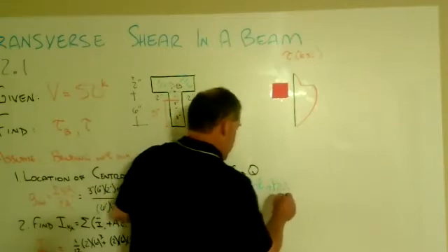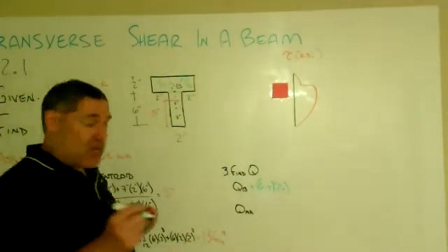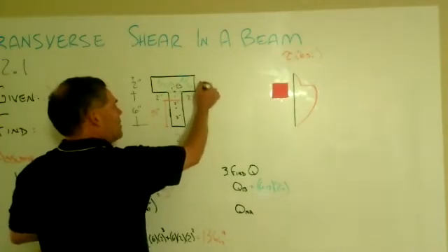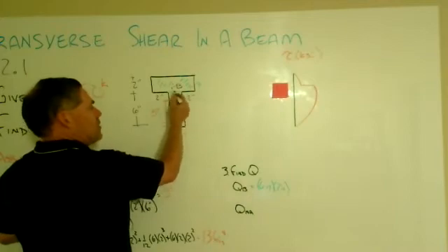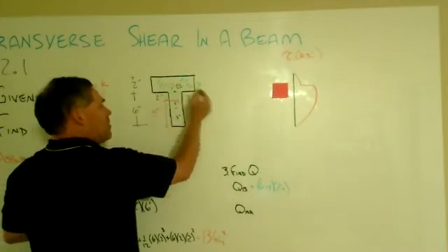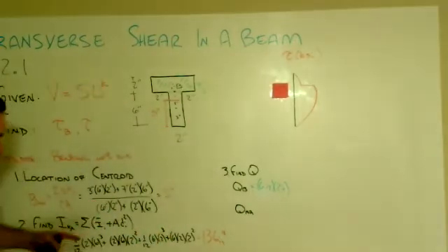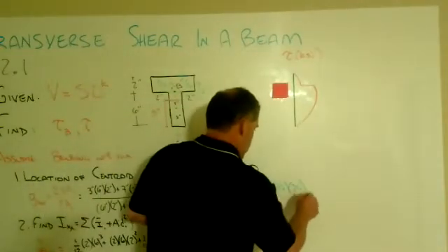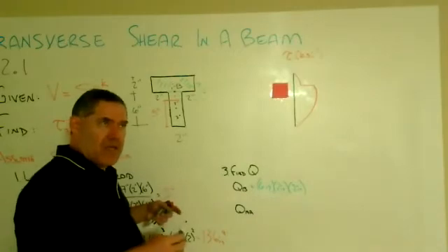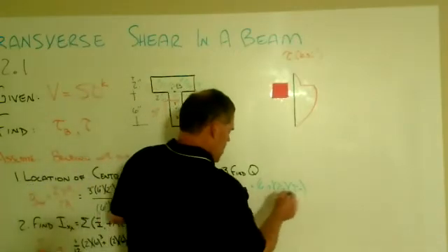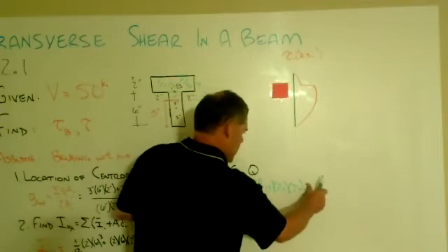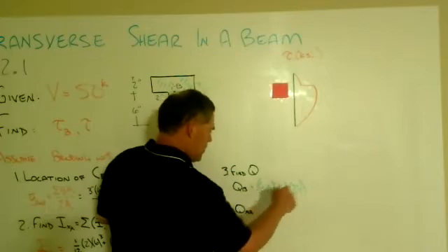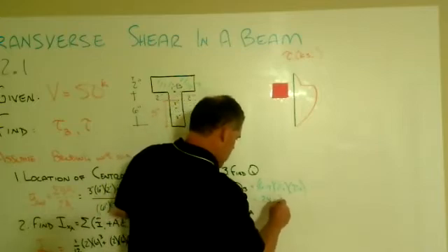That's the area, right? Now, its moment arm is with respect to our centroidal or neutral axis. So that's that distance right here. That'll go up 1 to get to the bottom of that rectangle, and then another inch. It turns out, in this case, it was the same as this moment term down here in the second moment of area. So there's that 2 inches. So I'll put that down below. So that Q is going to be 6 times 2 times 2, which is 24 cubic inches.